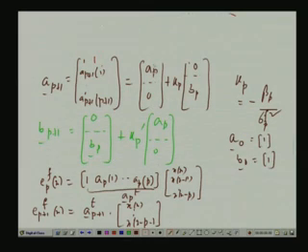The first term is A_p 0. So, forget the last entry of this vector, so you get A_p transpose x_n. The last entry of this vector, x_{n-p-1}, is to be discarded here because that gets multiplied by 0. So, what you get is A_p transpose x_n, and what is A_p transpose x_n? That is again E_p f_n, and K_p, K_p is what?